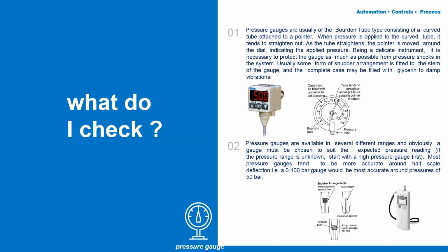That little device can measure pressure. You can clear its memory and it will record the peak and bottom pressures for as long as you've left it pressurized. So that can give you an idea. And if you expect that some random pressure drop is causing the machine to fault, this might be a way to tell you, did that actually happen? The minimum pressure recorded was 6 psi. That might tell you there's an issue. Or the maximum pressure recorded. Now, it doesn't tell you when that event happened, but it would be the first step in determining whether more pressure measurements and perhaps a data recorder would be warranted.